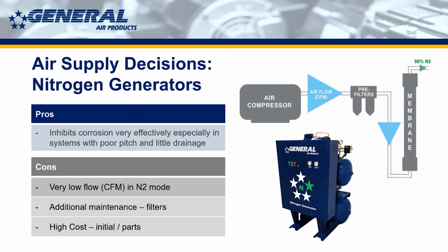What you do with a nitrogen generator is that when you first get it, you're filling your system with standard air. You're bypassing this membrane, right? There should be another line on this diagram that goes right around all this stuff and goes right to the system. Okay, and that's how the generators meet the 30-minute fill-up time. The reason they only meet the 30-minute fill-up time that way is because when you go through the membrane, you lose a significant amount of your flow. When I'm talking about a significant amount, I'm talking about over 90%, over 95% of your flow is lost in the nitrogen membrane.